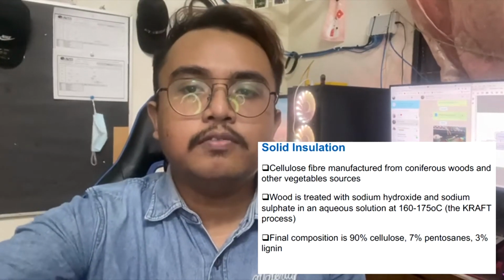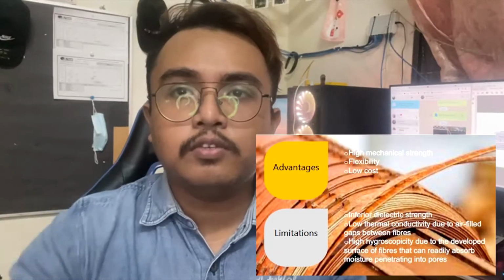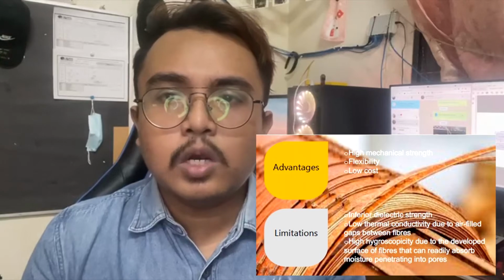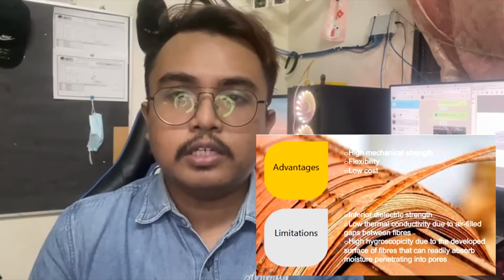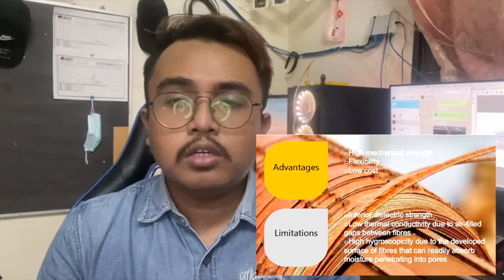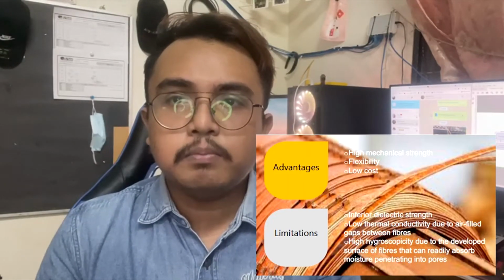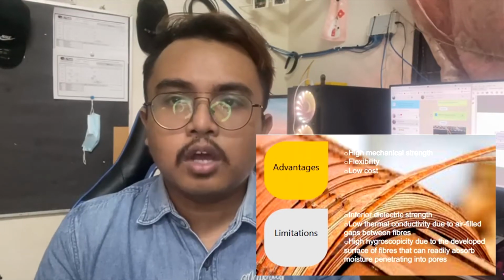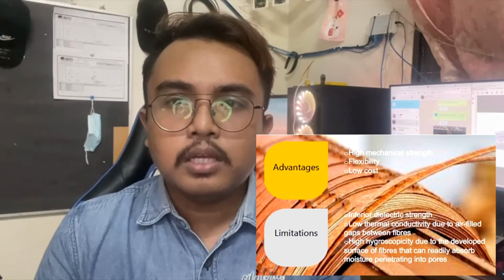The advantages of this insulation in transformers are high mechanical strength, flexibility, and low cost. The limitations are inferior dielectric strength, low thermal conductivity due to air-filled gaps between fibers, and high hygroscopicity due to the developed surface of the fibers that can readily absorb moisture.